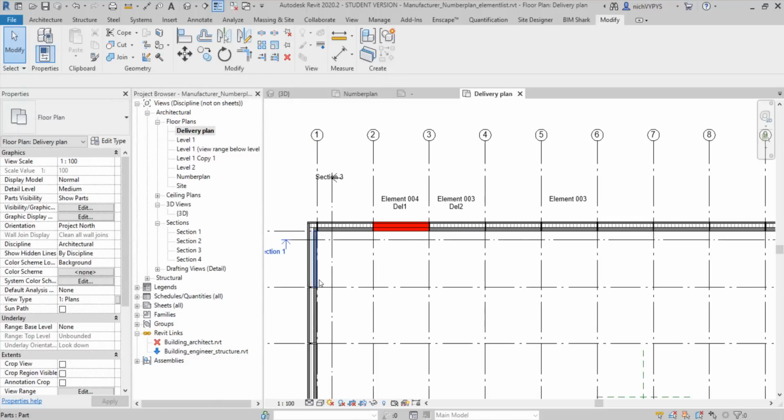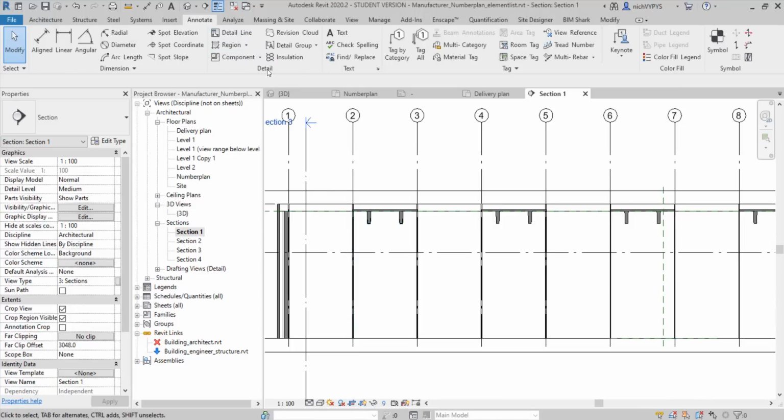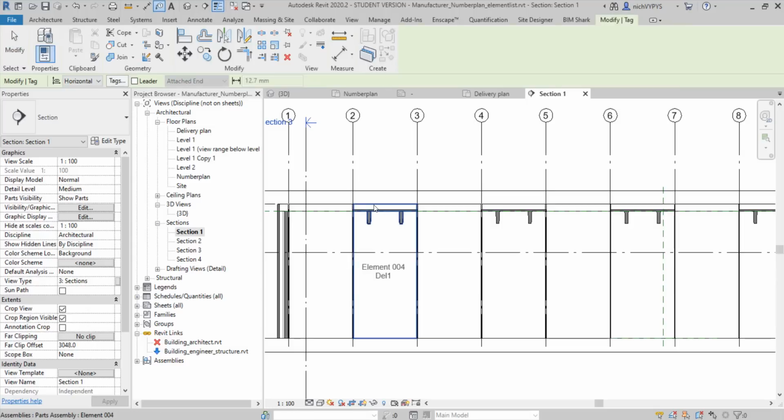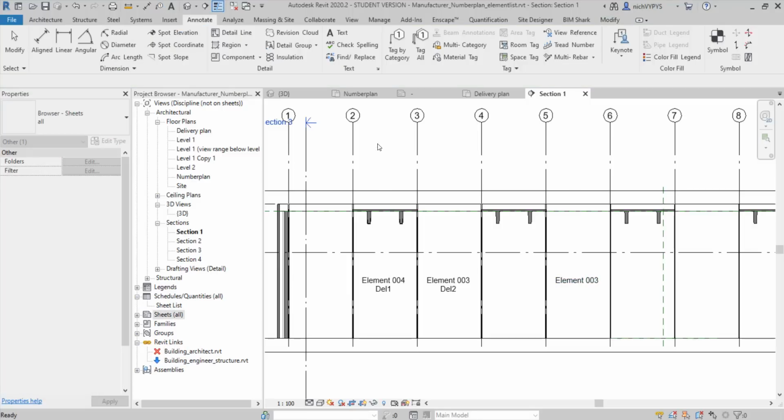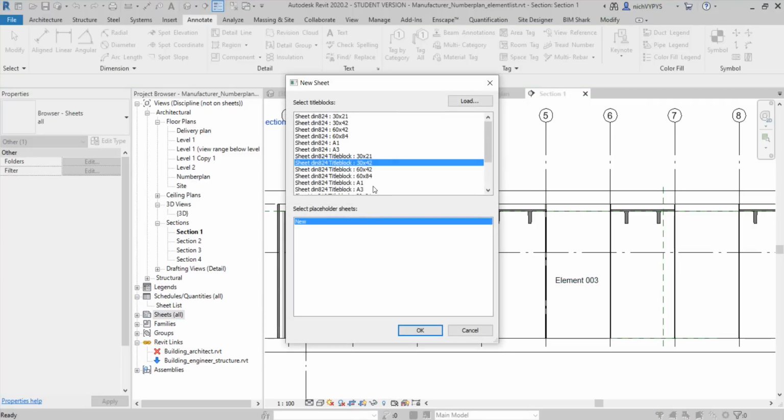And if you want to continue doing this, then you need to duplicate that specific filter that I made and then apply it. You can, of course, create facades or elevations, and since the information is on the assembly, it's just by adding tags to this view. And there's also a place where you can say tag all, so you don't need to place a tag one by one.